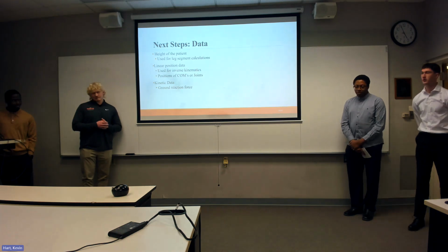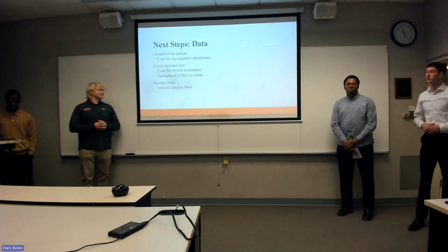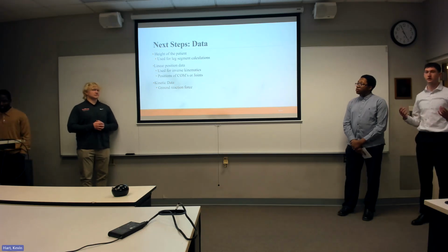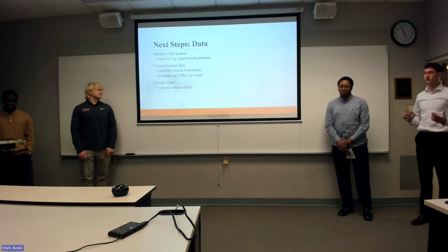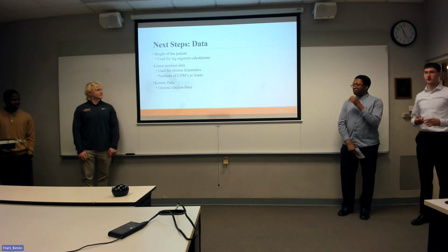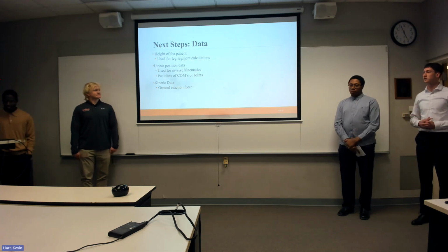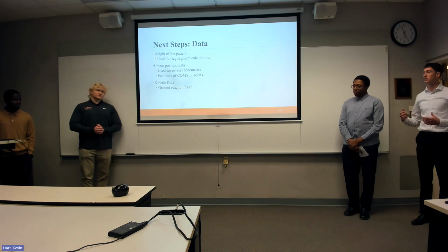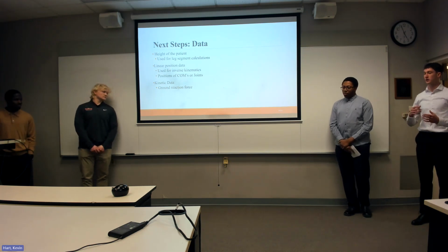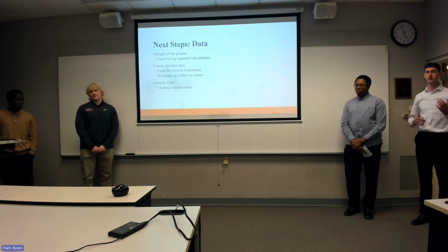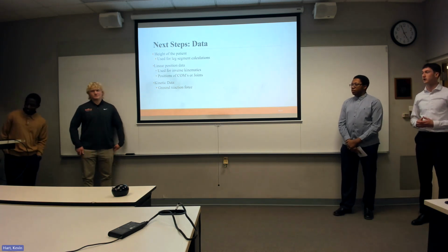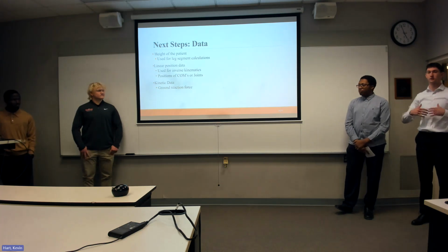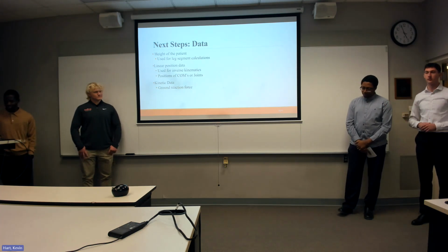And so our next steps would obviously be building the actual simulator, but then we would need real patient data. So we would need the height of the patient or use the leg segment calculations. And then we'd obviously need the linear positions to do inverse kinematics and then transfer that to joint angles. And then we would also need the kinematic data, specifically the ground reaction force, in order to determine, when we run the simulator, if the gait is improved or not. And then that data will be output into a spreadsheet, and then the doctors can look at the simulation results and determine from there as well.